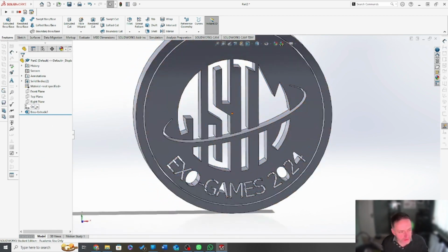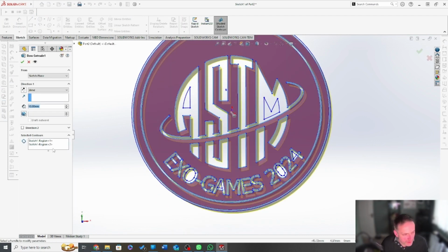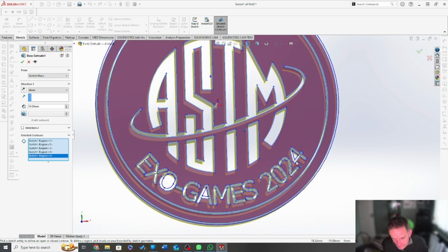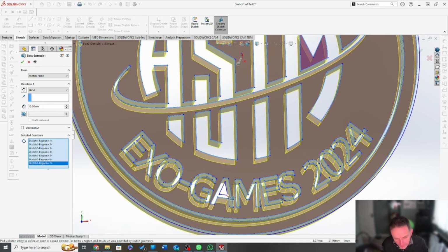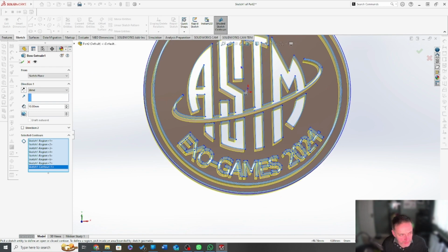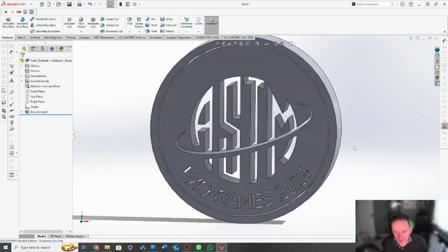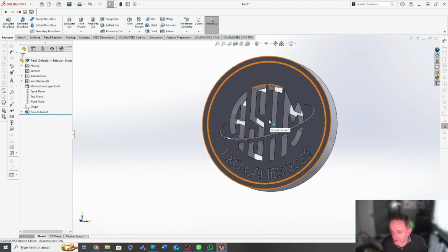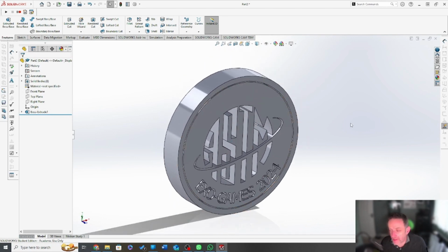See there, it's not quite captured all the other bits that I wanted it to, so I'll just edit that out. And then again, come in there, and to that portion there, and come on there. And you see, really, for those of you who are brand new to using Solidworks, it's like a colouring in exercise. So I click OK, and there we go. We now have an estimate of how that coin will be, and I could almost print that and make my own. But the trouble is you would need all my dimensions to be able to do that.